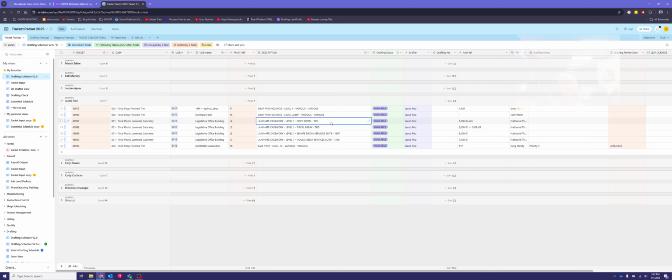So let's go ahead and jump right into looking at our arc reference here. They're calling out elevation view 1 on page I08-04. And if you notice to the right of that, it does say SIM next to that, meaning that it is similar. Occasionally an architect will be a little lazy and they might write similar next to a view.